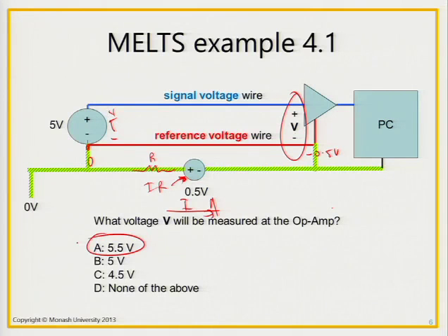Okay, so the tricky bit here was that this is 0 volts and now this is minus 0.5 volts. So all of you who got A were awesome. A for awesome. Yeah, so this is now minus 0.5 volts, and the difference between these two was 5 volts here. And so now this is 5.5 volts. Okay, so this is an instance where this ground wire, or this earth loop, causes a difference in voltage between 2 points where it's connected, and that's a problem.